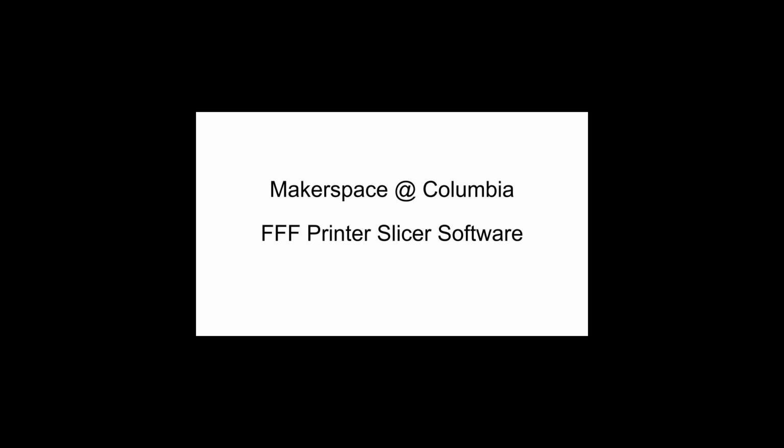Properly using slicer software is one of the most critical aspects of creating a successful 3D print. Slicer software is what generates the instructions for the 3D printer to create your object. It begins by taking your shape and slicing it into layers. It then generates instructions for the printer to create each of these layers, which it successively builds up.